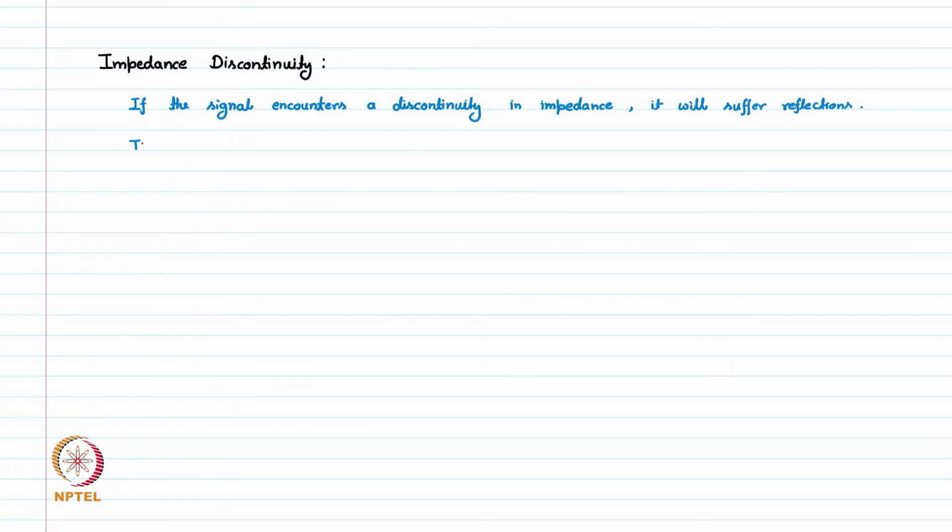This will happen when a signal encounters a via in its path, which is a very common case in PCB design. Many a time this trace ends up at a via, which is an impedance discontinuity.